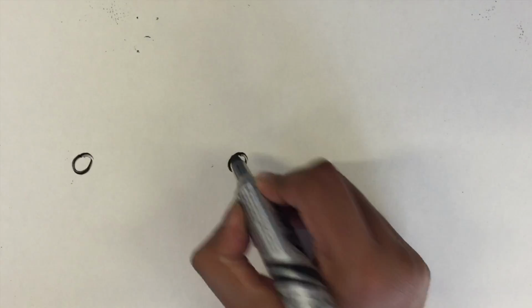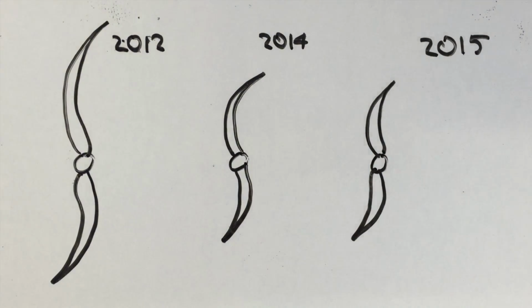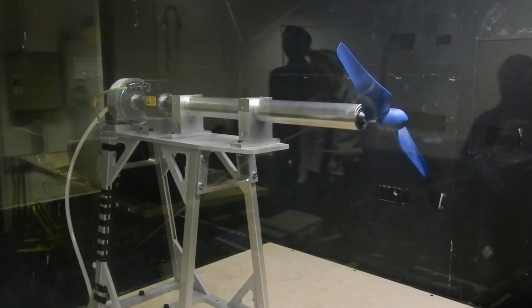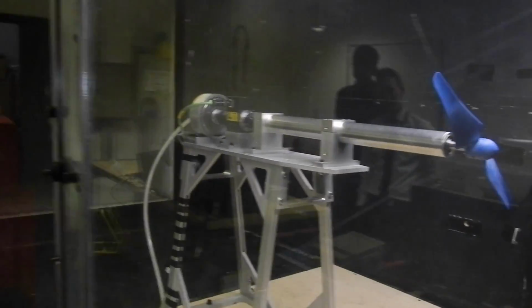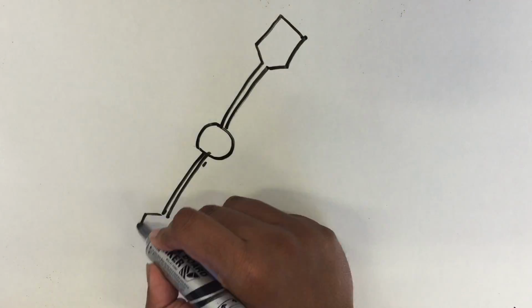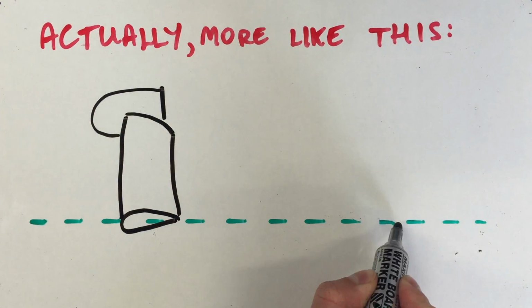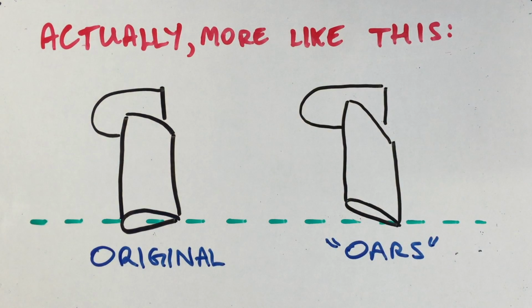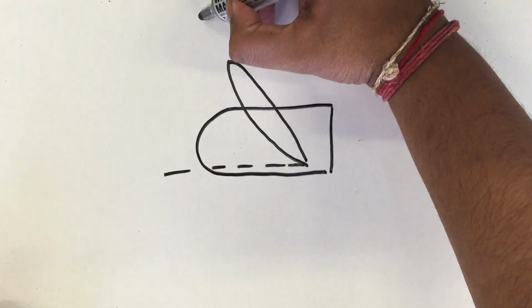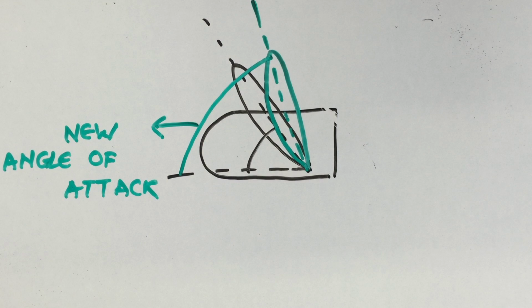Additionally, like us, all of the other groups failed to self-start. This is likely due to a continued reduction in turbine diameter from previous years, whilst utilizing the same testing equipment. The result is too great an inertia for the turbine to overcome, while still generating power efficiently. A possible way to self-start would be to essentially make the blades into O's and turn them to catch the oncoming wind. However, such a turbine would be very inefficient in generating power. Thus, we can conclude that we would need to twist the root of the blades to a higher degree if we wanted the turbine to perform better, given the same constraints and the self-start.